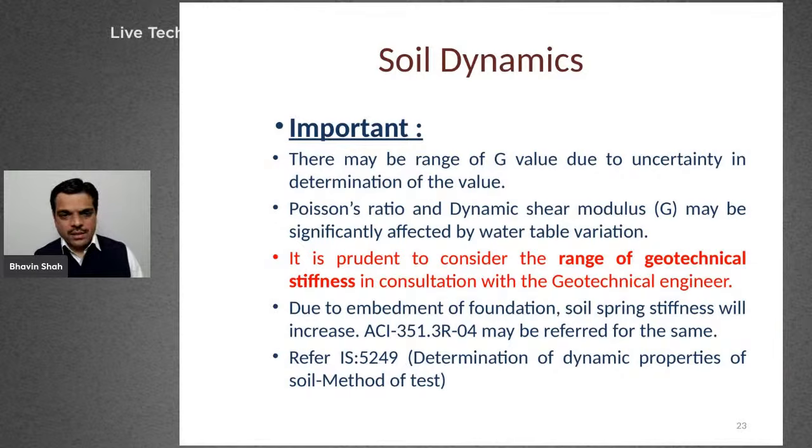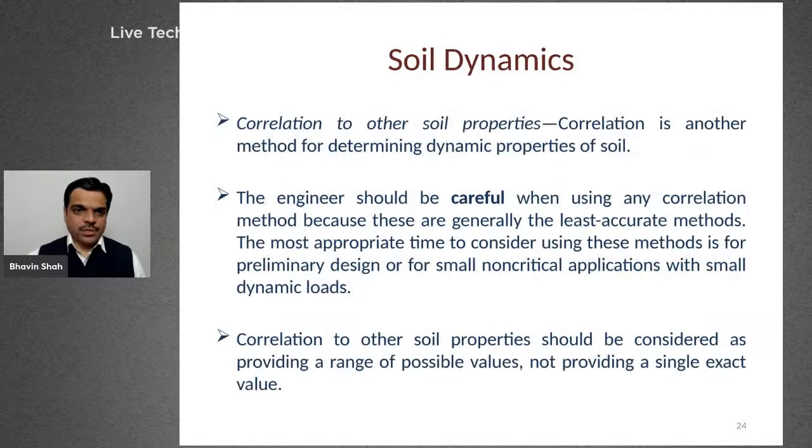One more part, due to embedment of the foundation, always the foundation will be embedded in the soil, and because of that the soil's spring stiffness will increase to a certain extent, and ACI 351 is suggesting certain formulas for the same, so it may be referred. And IS 5249 can be referred for determination of the dynamic properties of soil, method of test.